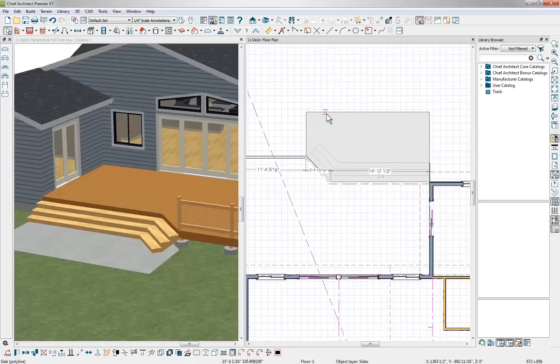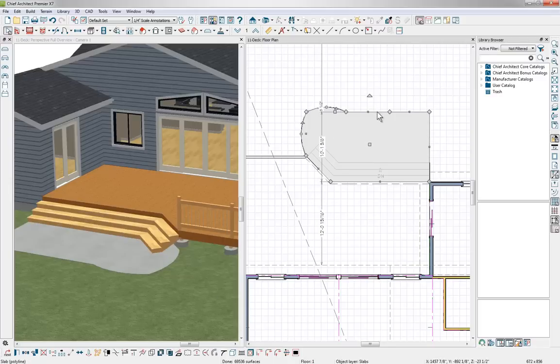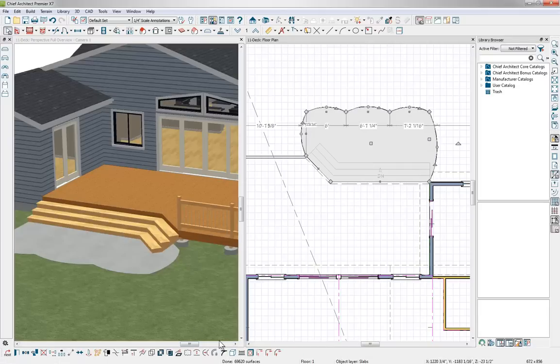And then I want to put in a couple of other breaks. We'll drop a break in here, and hitting the 3 on my keyboard, drop another break in here. And now I'd like to put some arcs, change line to arc in this area. So I'm going to select this line, change it to an arc, select this line, change it to an arc. I'm just going to go right around and click on all these edges and change them all over into an arc. And once I've done that, now I can start to play with and get a nice design of what I'd like the shape of this to be.